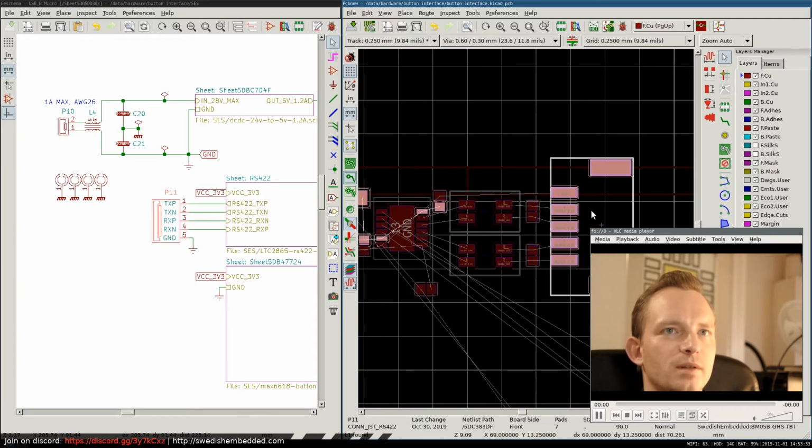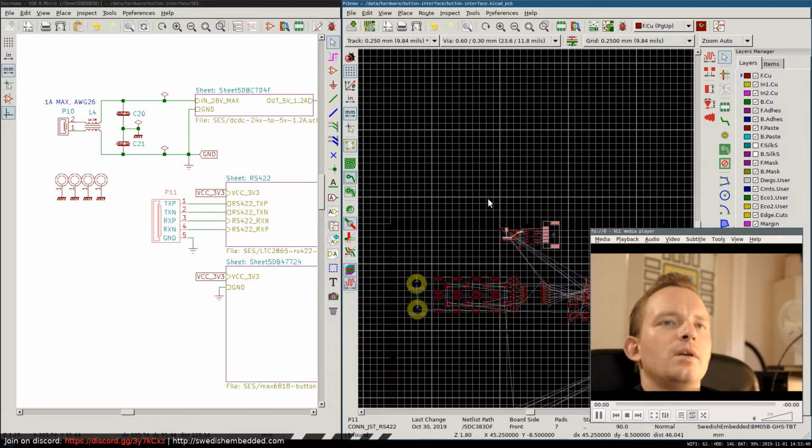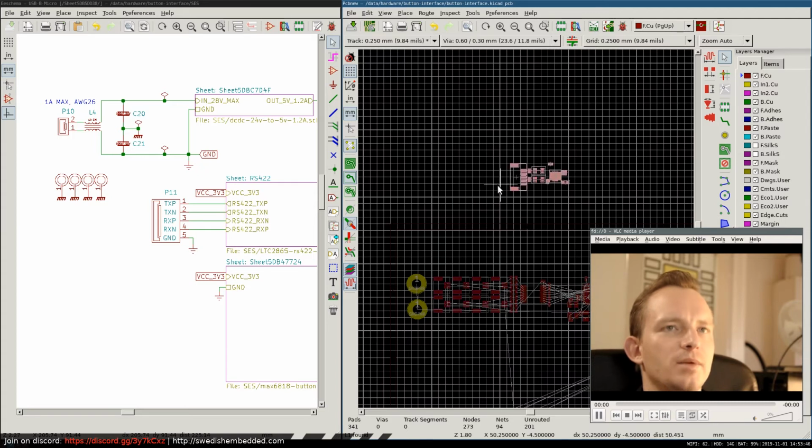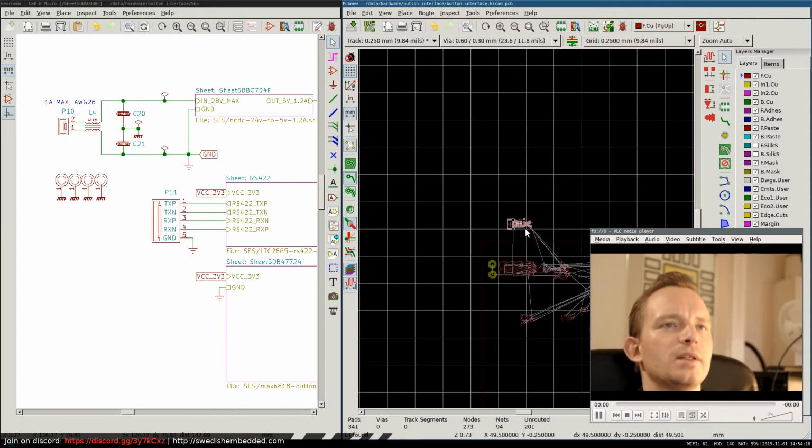This is a very nice fit. So everything can be very close together. However, what I'm thinking here is that it's quite likely I will change this connector because I would ideally want to have the power here. Then I'll just add one pin to this connector, and then I can eliminate this connector. I think that would be ideal, because both power and data are going to be going through the same cable with multiple leads. So that actually makes a lot of sense.